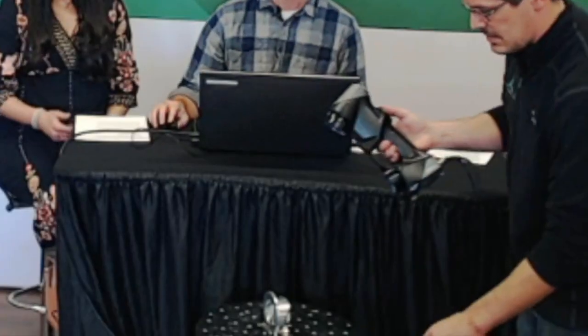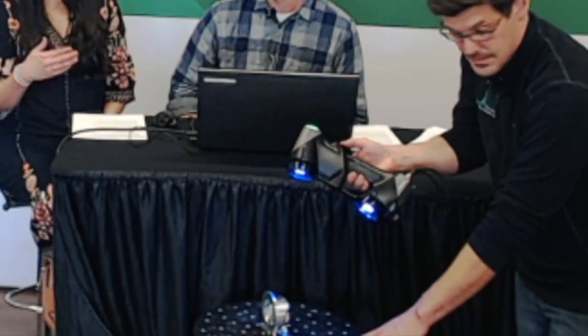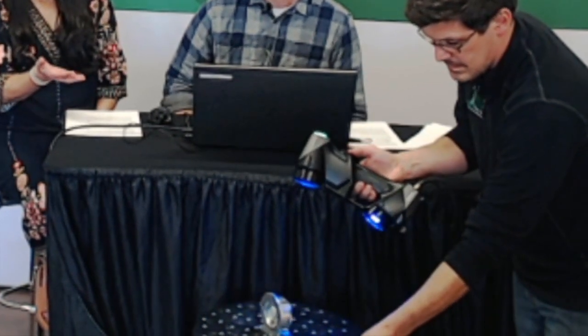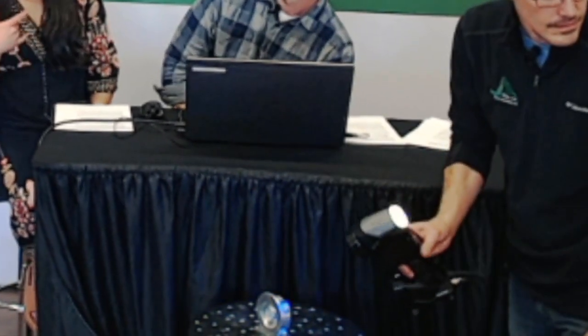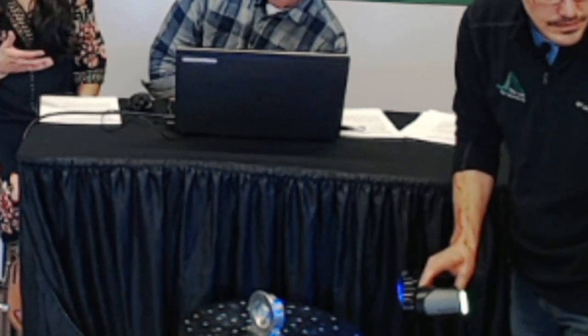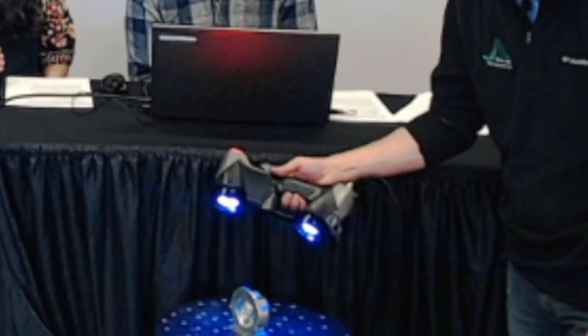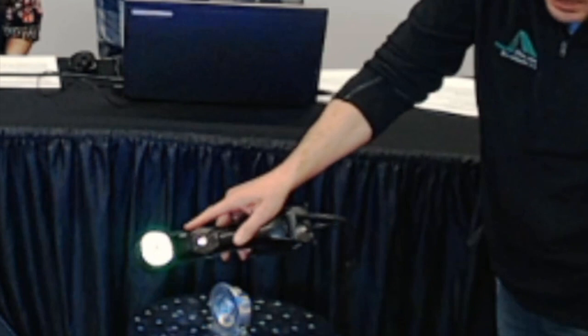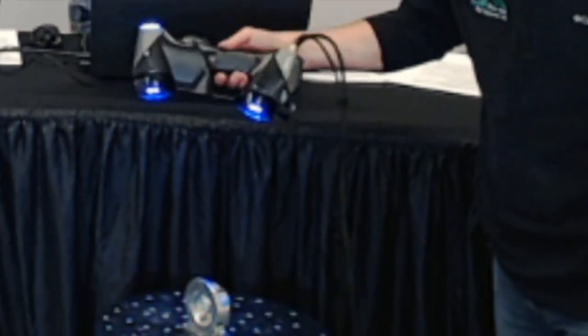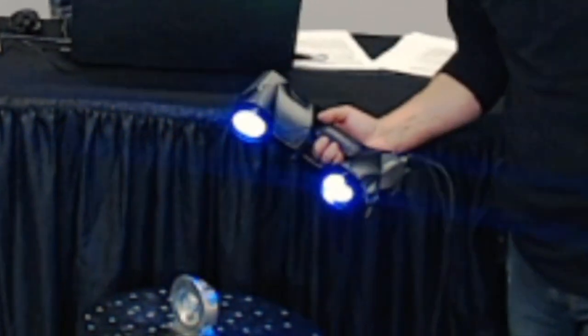Oh, sure. So while he's doing that, just a quick thought about the scanner itself. He's using a Creaform HandyScan Black Elite scanner. This has the blue light laser technology, which is the best on the market at this point. It's going to catch those reflective surfaces that you see. The point to surface detail is going to be 9/10 of a thousandth of an inch. And this scanner's got 14 of those laser lines crisscrossing each other to capture that data, and you see how quick it went.